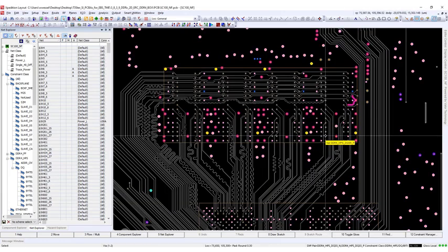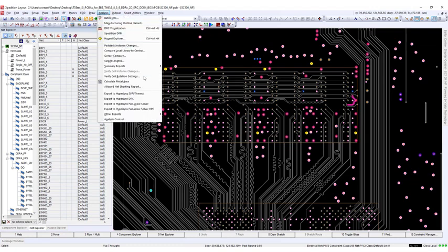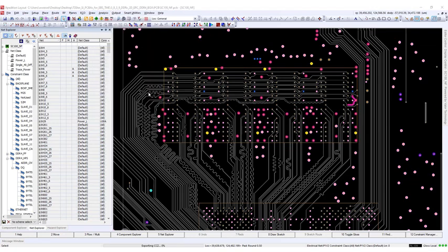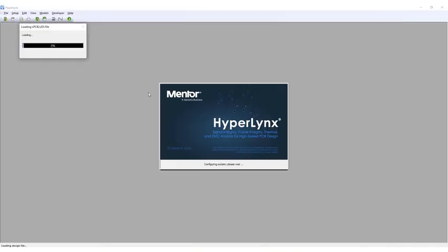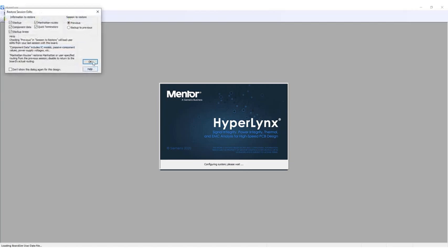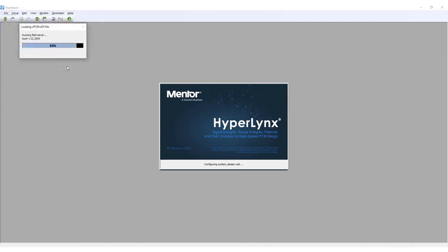After SEC constrained, routed and tuned the whole board, I want to ensure the routing quality of the DDR4 interface before the board will be handed over to Rory, the SI/PI expert, for the final sign-off. This left-shift approach not just reduces the time for iterative cycles between me and Rory to fix issues, additionally, I can learn and make my own experience to avoid typical SI issues in future.